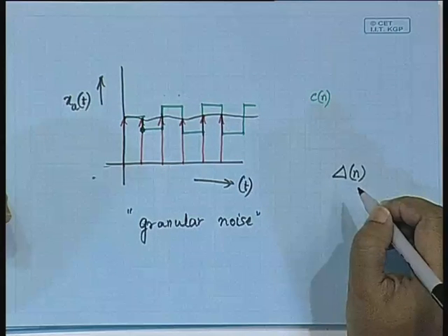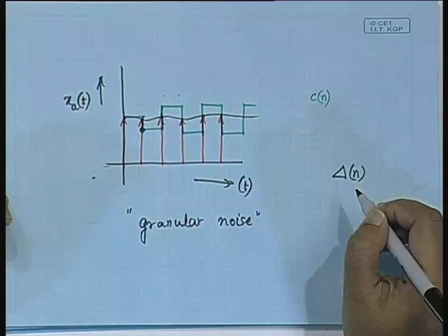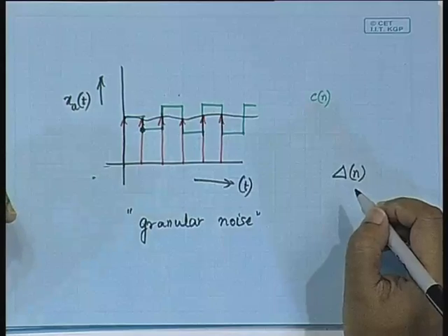Now the adaptive delta modulator is in fact even more required for the speech signal. For non-speech kinds of waveforms, situations where sometimes it is fast varying and sometimes slowly varying may not arise that frequently, but look at the speech waveform. Whenever you have voiced speech, you are going to have sharp variations in the signal. So there the slope overload is very important.